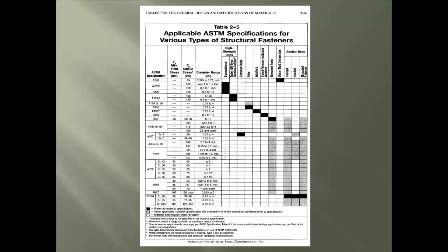Second example, what material can be used for shear studs? First, find a column that covers shear stud fasteners. Then look for the dark colored box, which reveals the designation of A108.